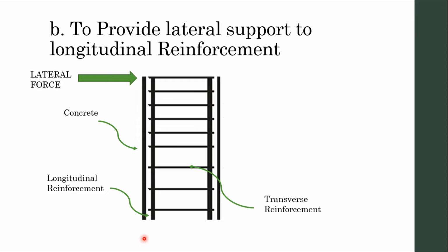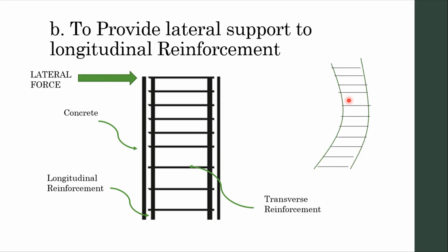So, for example, meron tayong lateral force na tumutulak, and this is our longitudinal reinforcement. So, when a lateral force is applied, tama ba na kapag may longitudinal reinforcement siya, ganyan siya magbabakel, di ba? So, hino-hold niya yung longitudinal reinforcement together when deflected due to the lateral force. So, parang sama-sama silang magde-deflect.